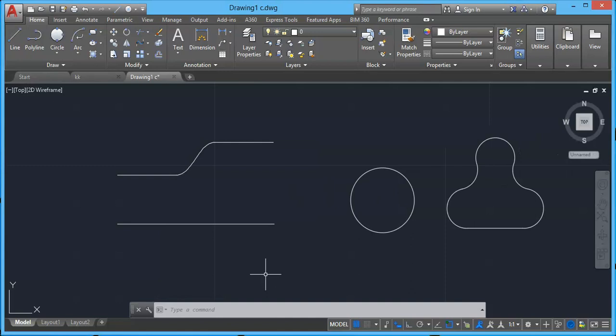Let's press Ctrl Z a couple of times, and let's look at this geometry. In this case we have objects as completely separate units. We have this line segment, and we have circle arcs here, here and here. All of these objects are completely separate. Now if I want to join them into a single unit, you can do that with the join tool.